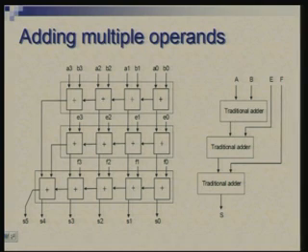So, we will look at the question of addition of multiple terms. I am not quite showing a multiplier here, but a circuit which adds 4 numbers. In case of multiplication, these numbers will happen to be those partial products, but let us say we have 4 arbitrary values to be added. You will have one adder which adds 2 terms, next one adds third, next one adds 4th term. So, suppose we put the usual ripple carry adder for each of these stages, then what is the consequence?